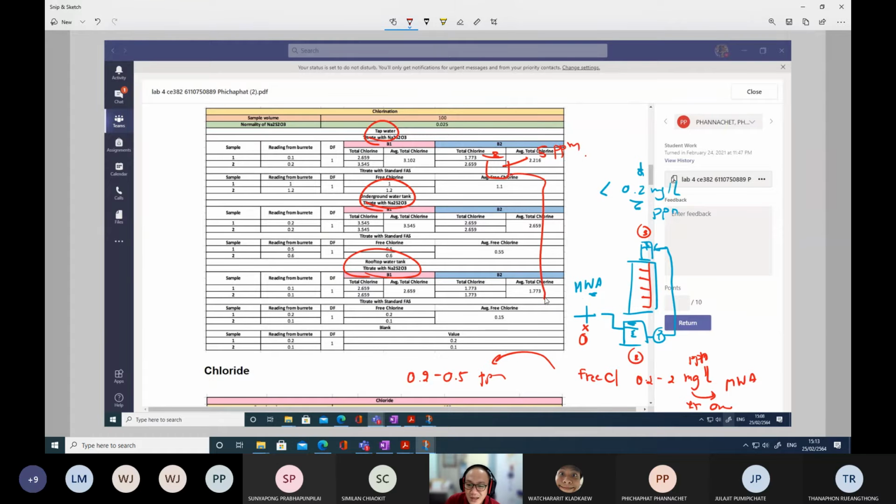But during transportation, a certain amount of chlorine is lost. It's the nature of chlorine. So not all will still be present. Some certain amounts of the chlorine may be vaporized. So at the consumer's house, it may reduce to around 2 milligrams per liter or slightly higher.